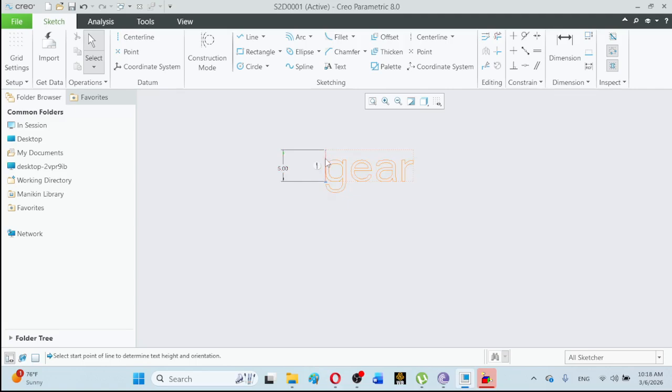Here as we can observe that the vertical constraint has been applied. If I have, for example, deleted this vertical constraint here, I can press and drag, and can place it at any random angle. And if I want again that this text is to be placed horizontal, then I can use this vertical constraint, and I can make this line to be vertical, so this text has been placed horizontal.